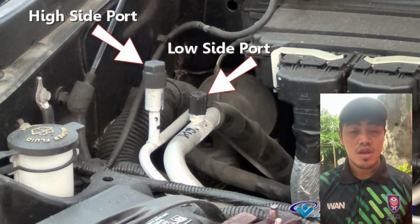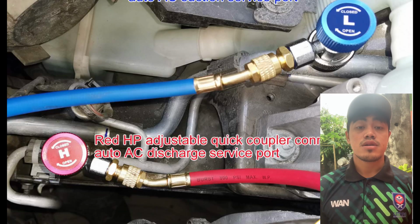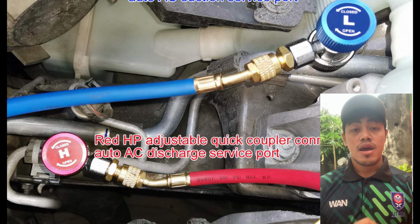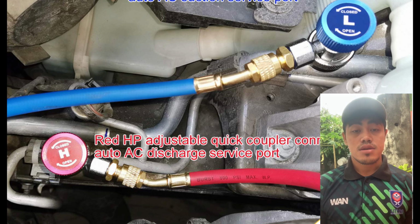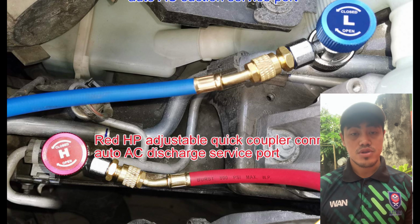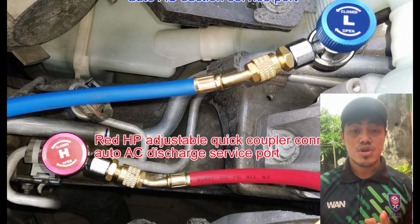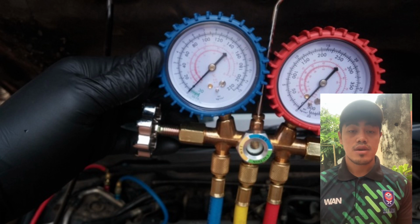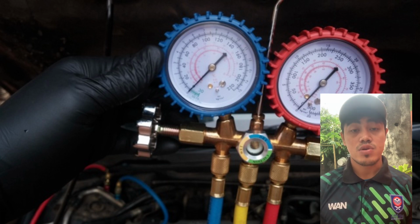the port cap. After that, connect the red color hose gauge to the high port, and then connect the blue color hose gauge to the low pressure port. But make sure both of these gauges are at zero, and make sure also the valves are in closed position.